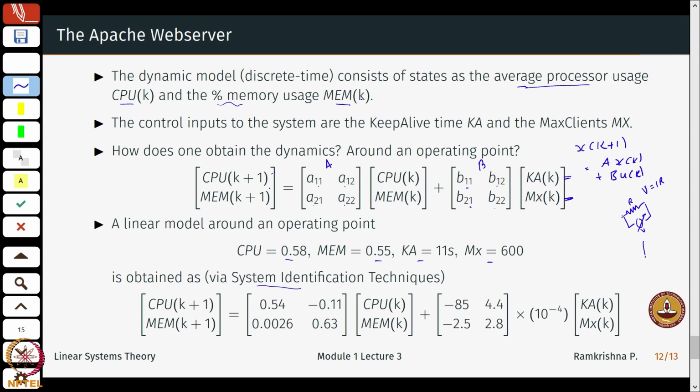So, what I do, I start from 0 volts till some 20, 30 whatever volts. I just see how the current changes. So, here I have the voltage and I just plot it against the current. It should ideally give me a straight line, and the slope here is the value of R. So, this is a very simple identification experiment by just looking at some input output data.